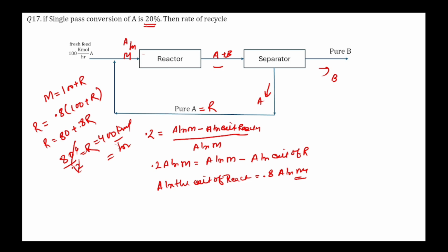Okay. For laminar flow of a fluid through packed bed of sphere of diameter d, the pressure drop per unit length. Apply Ergun equation for laminar flow. Very first, you write the Ergun equation. When you apply the Ergun equation, then cancel the turbulent term. The remaining will be the laminar term, and that depends on the diameter as 1 by d square.